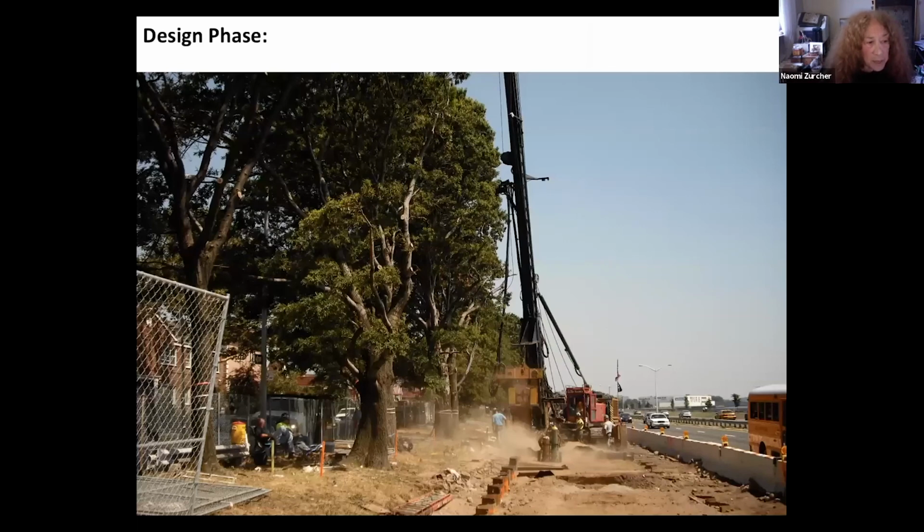The design phase determines how the project can be built in conjunction with tree and landscape protection needs. Construction equipment, drainage and grading, utility installations, storing of excavated soil, staging requirements, control of construction debris, spillage, washout, and sediment, as well as parking of project-related vehicles. A thorough understanding of all of this can contribute to discussions that will determine construction strategies that support protection.